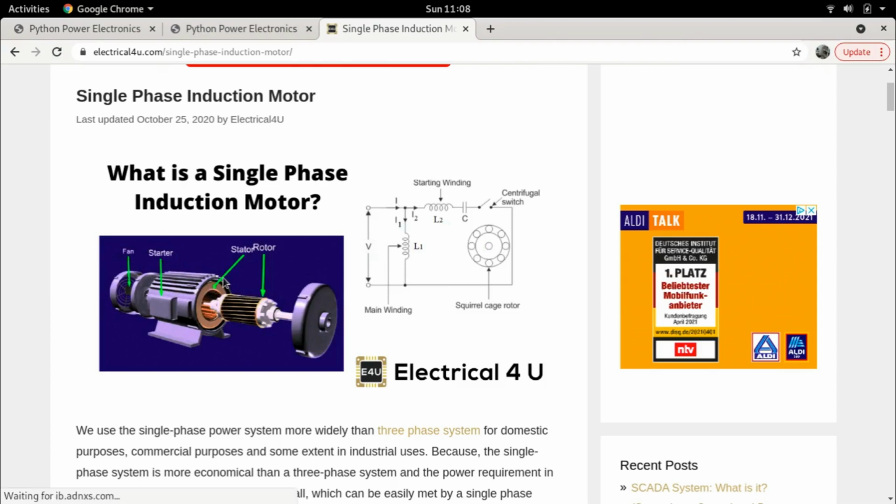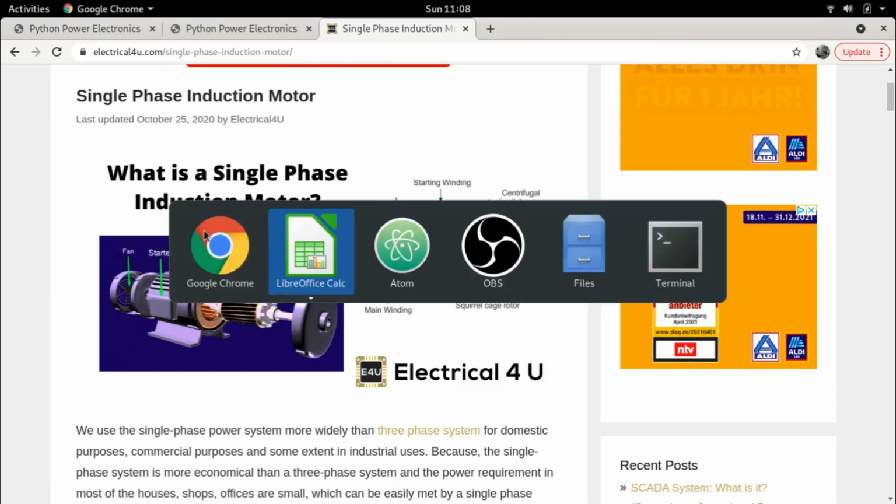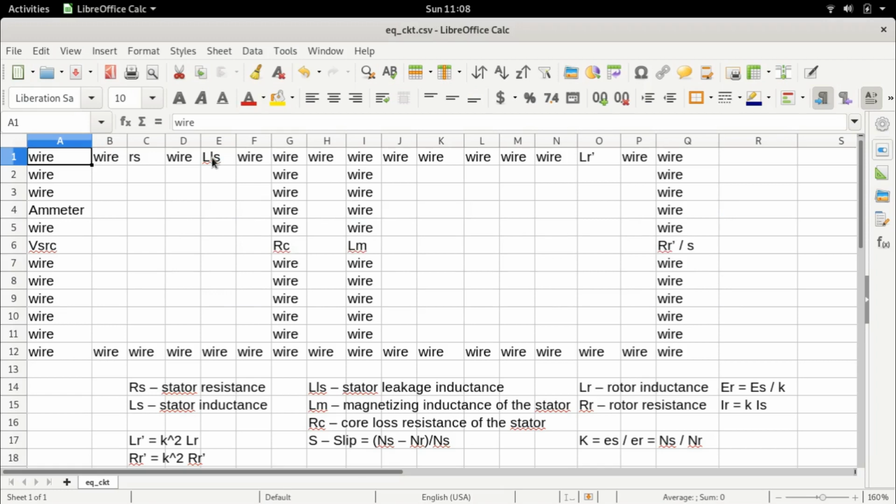It's not doing anything useful, that's all. So this leakage we have already represented by this leakage reactance or inductance of the stator. Besides that, we also have a stator resistance. This stator resistance and this leakage inductance will result in a certain voltage drop that does not do anything useful.